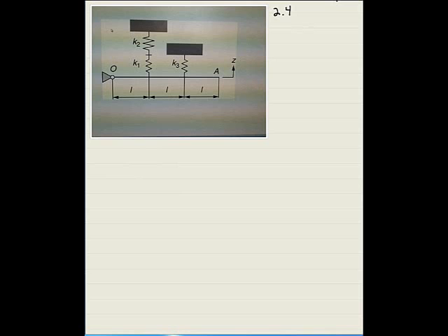Nothing wrong with that. I think that's okay. I like to kind of go back to the fundamental concepts, and what I would do then is draw a free body diagram or write the equations of motion, either way, for this system with three springs, and then write it with one spring, and then say that the equations have to be equal. So anyway, bottom line, I want to write the equations of motion for this beam.